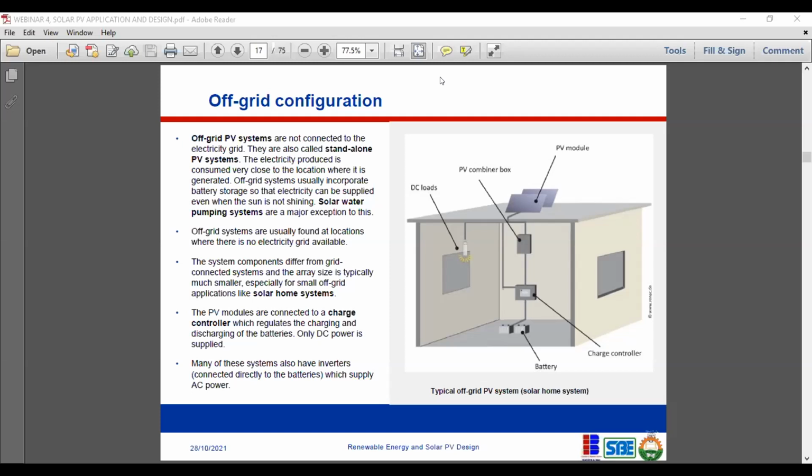Okay, in your own case, you don't have batteries. It's just an interactive inverter with the grid, and of course, you have a generator forming the grid in the system as well. Correct? Yes. My major problem is when I'm running the generator. I understand. So when you're running generators, because you have a large contribution from the solar system, your generator is running at a very low load factor and that is affecting the generator.